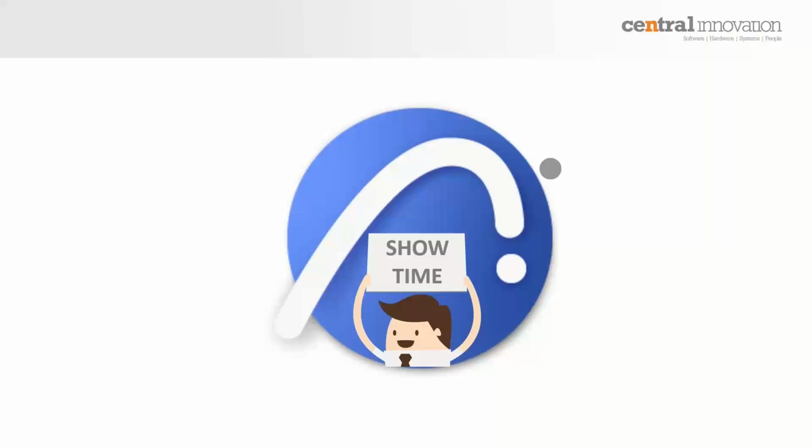Now, round tripping, or this way of sending one model around and then sending it back, is not advisable, it is not recommended, and it's far from a good idea when using IFCs, because you actually want to use the native software. Otherwise, there's going to be far too many changes that will need to be done to the file just to revert it back to its initial stage.